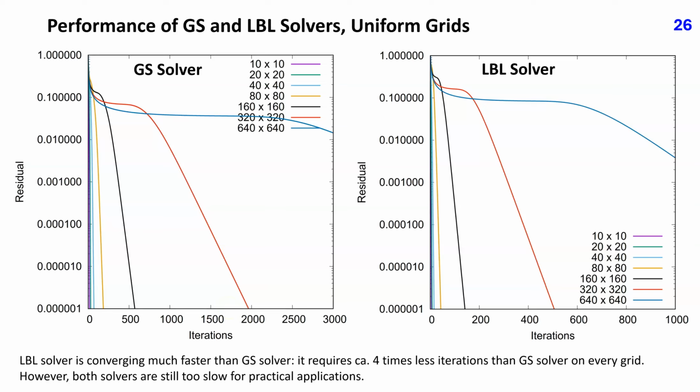However, the shape of curves representing residual norm history is different than in the previous cases. Rapid initial reduction of residuals is followed by a plateau with a very slow reduction, and after a while faster convergence rate starts, resulting in a straight line in the log linear representation. The convergence of both solvers is significantly faster when convection is present than in diffusion-dominated problems. On the same grid, less than 1/10 of iterations required to solve the Laplace equation is needed.